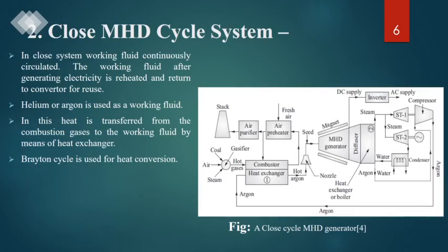But the remaining part of the ionized gas we can say is useless. So why is it useless? Again, the funda is the same. When we use the ionized gas at high temperature, some part, 25 to 30%, of the heat is extracted or converted into electricity, but the remaining part is already absorbed by the ionized gas, and the temperature of the ionized gas is reduced. So it does not work efficiently for the ionizing process and to produce electricity.